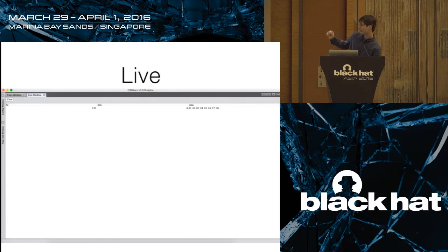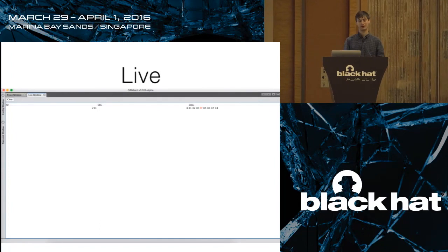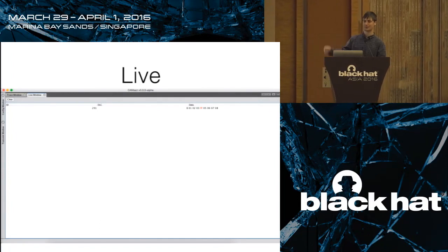This live view, very simply, shows you one row per CAN ID. And what changes is the data. And as that data changes, and this is a simple example, it gets highlighted in red, which might be a little hard to see on this slide, but as you get a byte changing, that literally changes color. And what this lets you do is look at like 100 different CAN messages at once. You can see certain things changing. You do something to the system, be it rev up the engine, stomp on the brakes, open the sunroof, change your position for GPS, and whatever's turning red is what's changing.